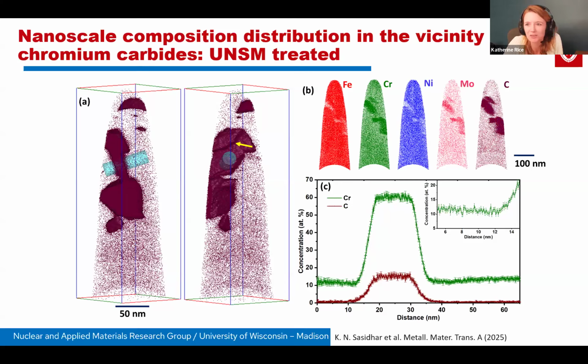And then this is a two-part question. Is there any further characterization to confirm the alpha prime martensite, as its lattice parameter is very close to that of the alpha phase? So alpha and alpha prime. We are nominally calling it martensite because it's a deformation-induced transformation here. At least we were happy with the characterization that we did, and we didn't see the need for really saying if it's different from alpha or alpha prime. So that's where I would leave it.